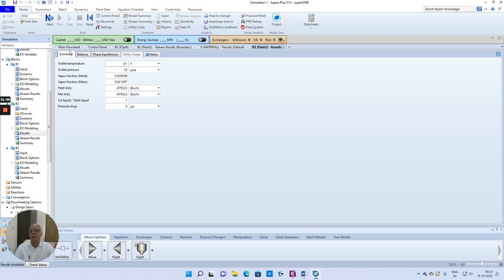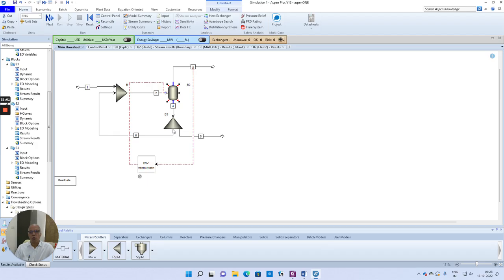Why is it so? Earlier the amount of feed entering the flash column was lower. Now more quantity is getting admitted into the flash column. All that amount should be reduced to 41. So this may be by chance, but you can think of analyzing what would be the changes of recycling either the bottom product or the top product back to the column, right?